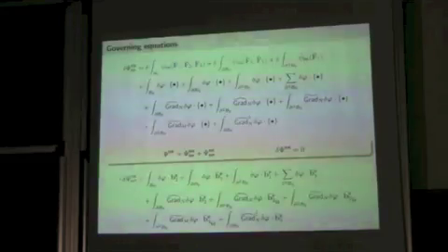If you look at the same thing on the surface, you see something as a work conjugate to displacement on the surface, so it's traction, basically. It's the surface traction, then this one would be the curve traction. These are the point forces. The rest, I would call them just generalized tractions. They are integrals over the surface and over the curve, and they are work conjugates to normal gradients in different directions or second normal gradients.